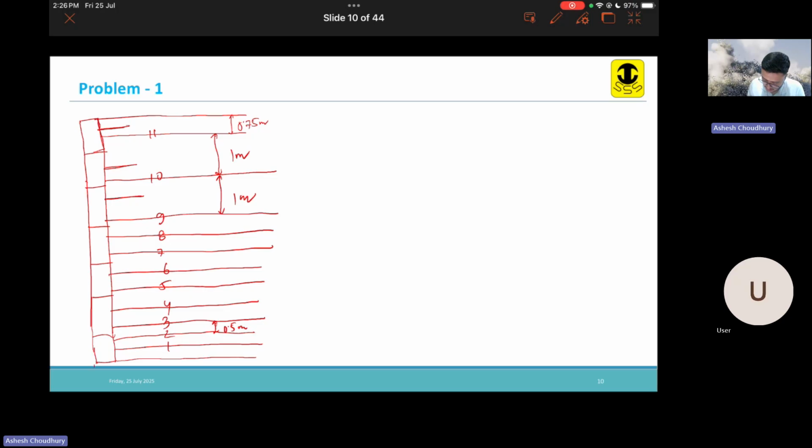At the bottom the blocks are properly connected, but at the top, if they are connected at only one point, then it will be unstable. So to stabilize these blocks, we insert these small strips of geogrid that will hold the facing blocks in position. Okay.